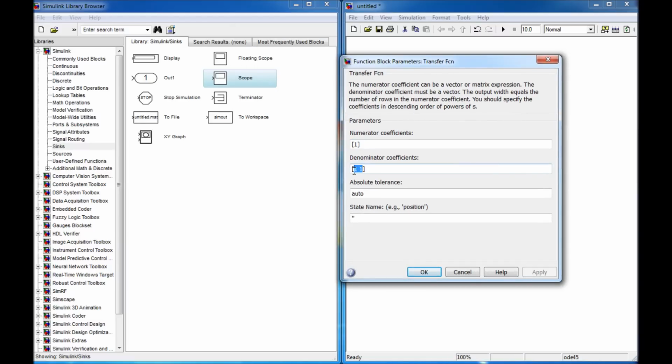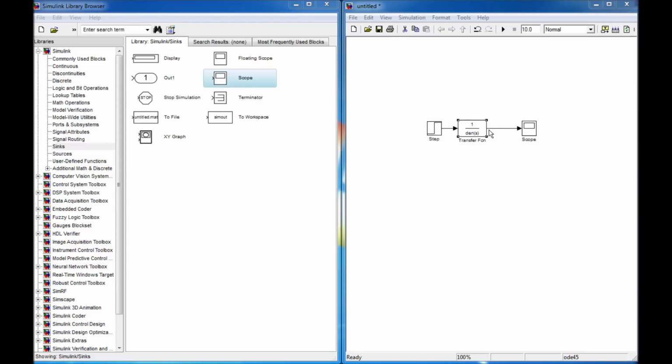So the motor we're going to model is a little Lego motor, and I will just give you the transfer function so that we don't have to derive it. So it's going to be 2.921 times 10 to the minus 5, comma, 0.0315, comma, 0.5048, then comma, 0. And if we make our block a little bit bigger here, we will eventually be able to see our transfer function.